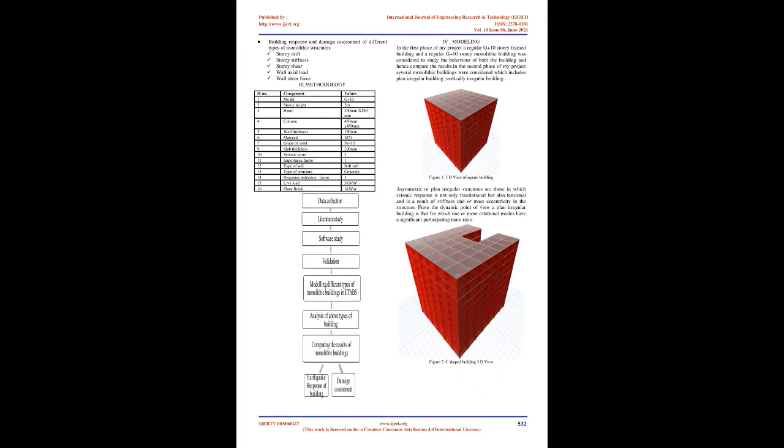The natural period of the building is calculated by the empirical expression prescribed in the code. The total design seismic base shear calculation and its distribution along the height are done as per IS 1893 Part 1, 2002. The seismic weight is calculated using full dead load plus 25% of live load. B. Modal analysis. Modal analysis, or mode superposition method, is a linear dynamic response procedure which evaluates and superimposes free vibration mode shapes to characterize displacement patterns. Mode shapes describe the configuration into which a structure will naturally displace.